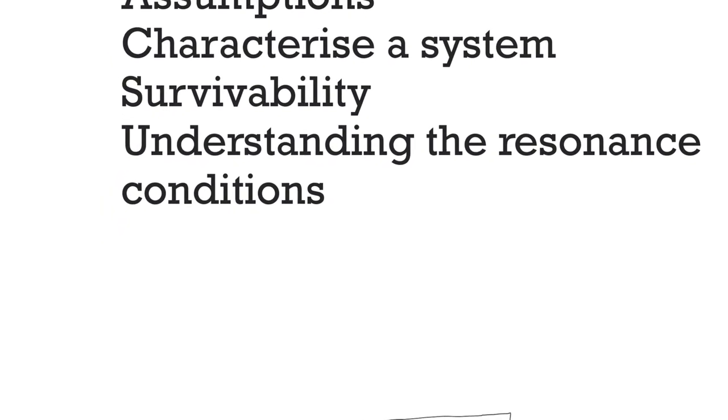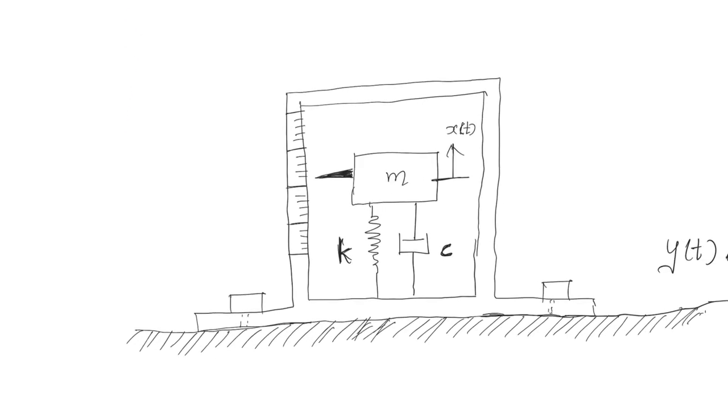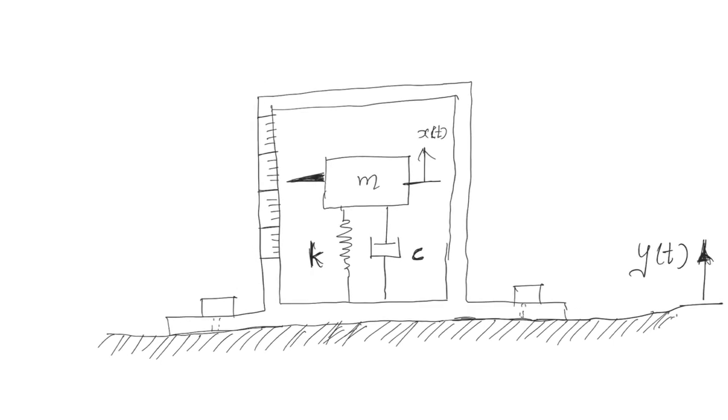So having established the relevance of vibration testing, let me go ahead and discuss vibration measuring instruments. Basically, vibration measuring instruments are transducers. Transducers, to put it in brief, are systems which can convert a physical variable to a corresponding electric signal. There are different types of transducers. There are variable resistance transducers, piezoelectric transducers, electrodynamic transducers, and all kinds of different transducers. I'm not getting into the nuts and bolts of all those, but a basic vibration measuring instrument, let it be an accelerometer or a vibration pickup, the setup will be something like this.